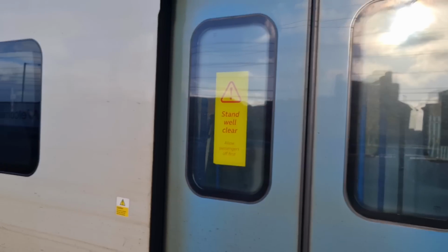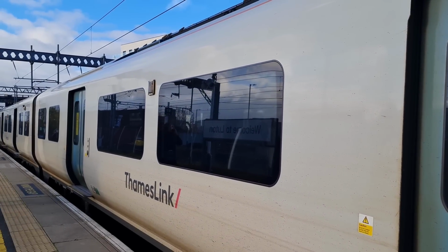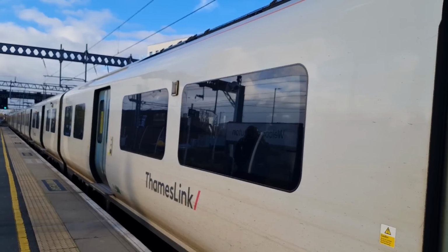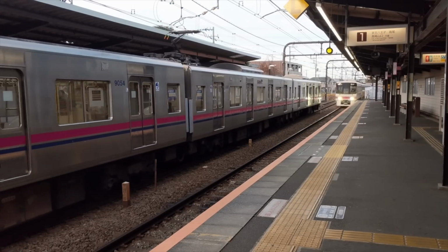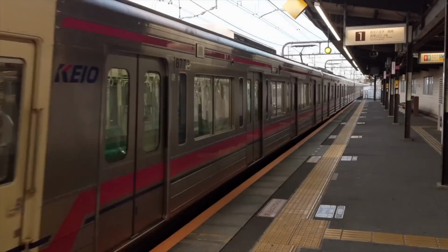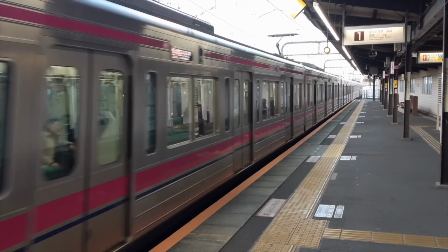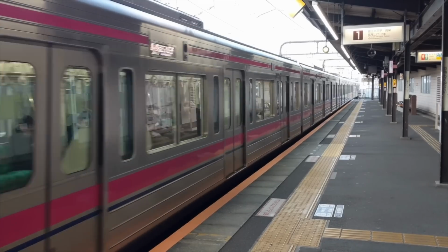So there you have it. Passenger train interface risk is managed through maintaining standard offsets between track and the platform. At the doors, the risk is further reduced by measuring and regulating the distances passengers have to step from platform to the door. Various factors need to be considered when looking at trains in platforms, including curvature, door position, gauge clearance, and the platform itself.